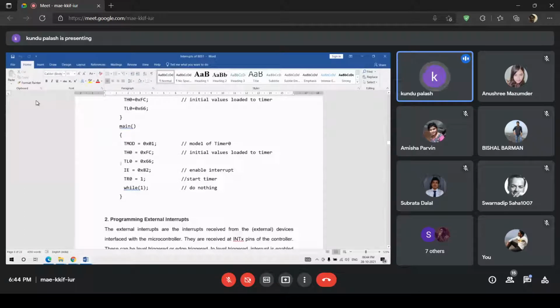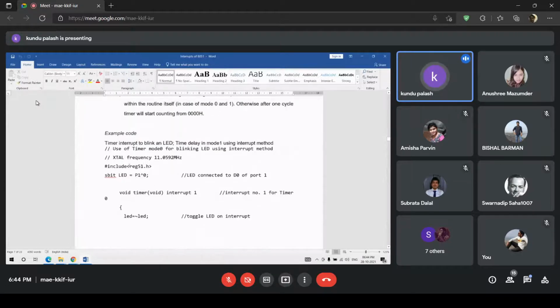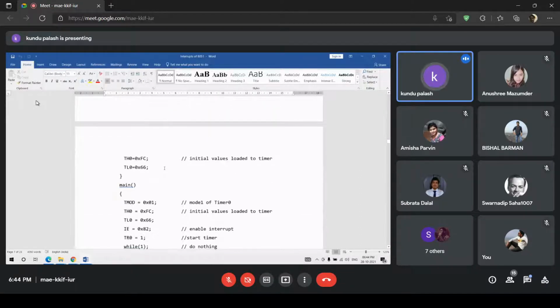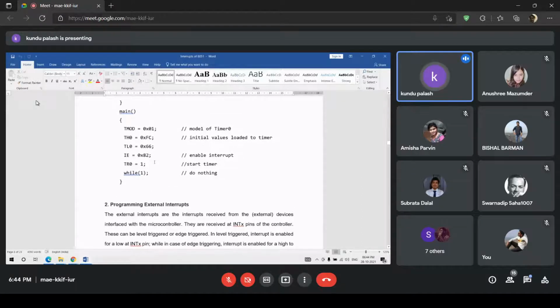And this is the body of the main program. The initializations in the main program in C statements are very simple. The same variable names can be invoked, but the variable names and data types are written within the header file reg51.h. If you do not use this include statement, there will be an error during compilation. And this is an infinite loop, so this is a never-ending program.